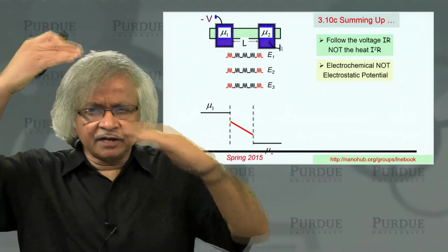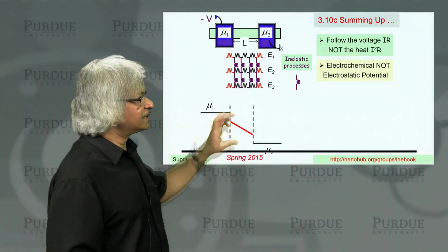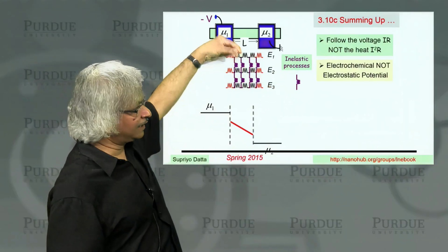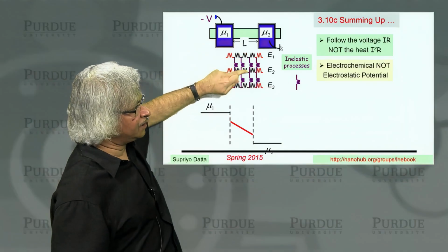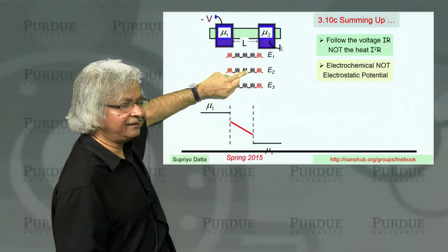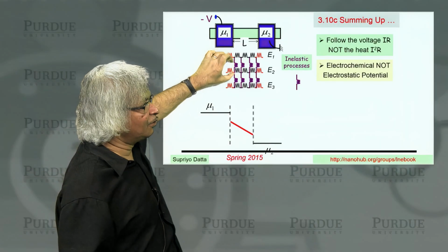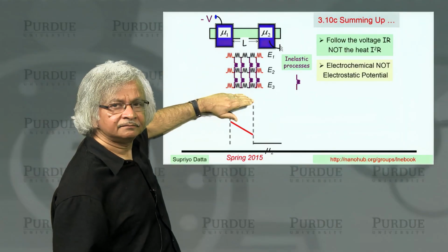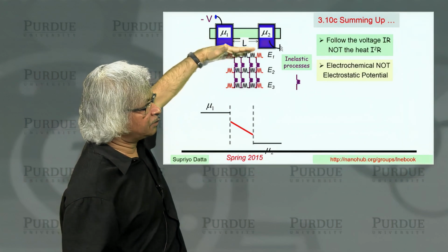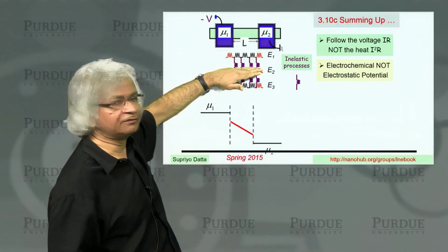Now, what does inelastic scattering do? Well, conceptually, what it tries to do is bring different energies into equilibrium. So you could think of it as a kind of a vertical resistor, one that connects one energy channel with another. You see, we have ignored these. But if you were to include inelastic scattering, pictorially what we would be doing is including resistors that go between energy channels. And these potentials here, of course, there could be one set of electrochemical potentials that is appropriate for this energy, another set for that energy.